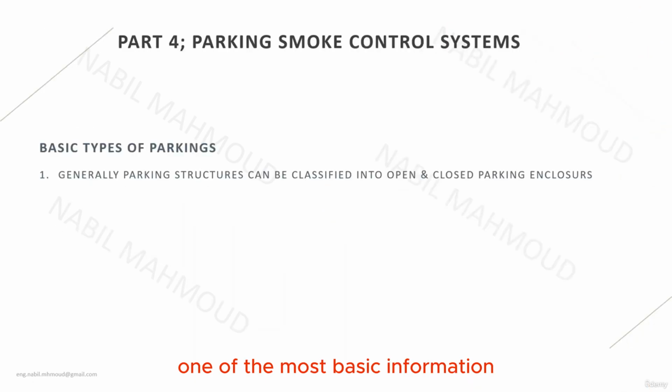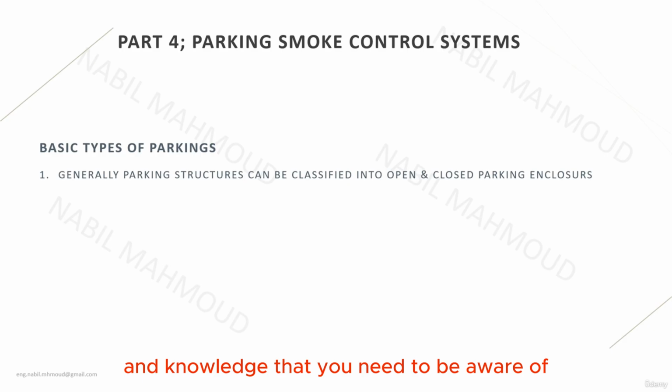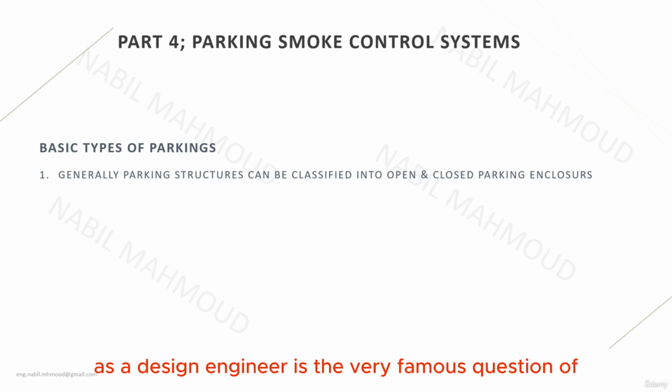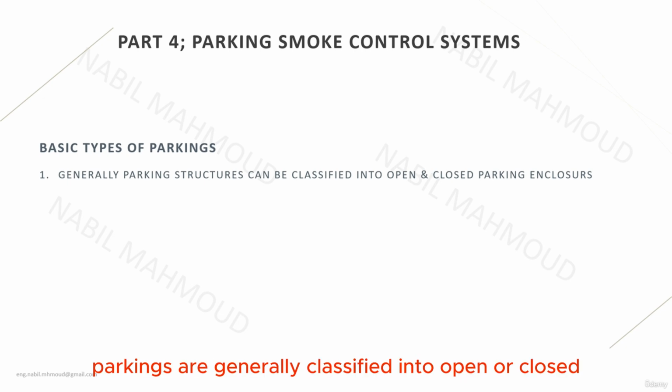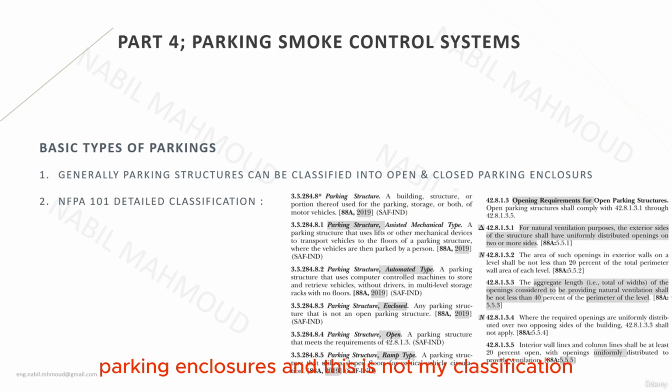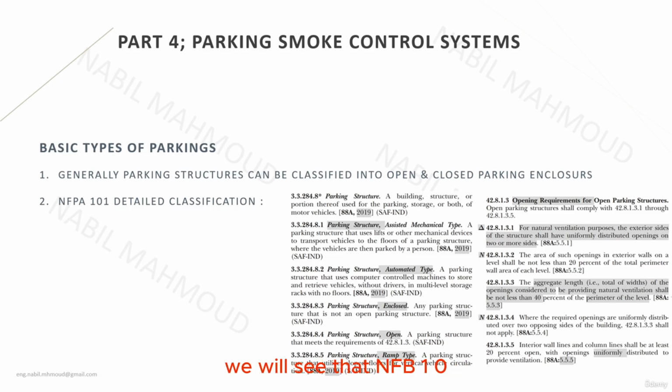One of the most basic pieces of information and knowledge that you need to be aware of as a design engineer is the very famous question of what are the types of parkings. Parkings are generally classified into open or closed parking enclosures, and this is not my classification. This is the classification of NFPA 101, which is the NFPA Life Safety Code. If we read the paragraphs on the right side of the screen, we will see that NFPA 101 is giving a detailed classification of the parking enclosures.